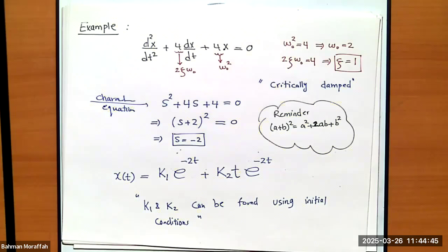And again, remember, I need two initial conditions. So I have to use my continuity conditions for a circuit, which means VC at time 0 negative is the same as VC at time 0 positive. IL at time 0 negative is the same as IL at time 0 positive. I need to use these two conditions to find those initial conditions that I can actually solve the circuit with, right? So let me give you a recipe as to how we can apply this differential equation to a second order circuit.